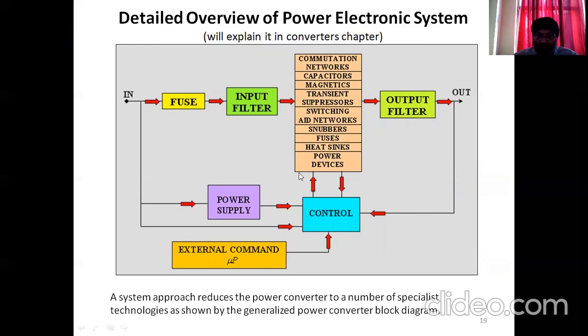And this power processor is being controlled by the controller over here. We already saw one building block in the previous slide. This building block controls or sends control signals and receives some output. Based on this, it makes decisions whether to increase the switching frequency or decrease the switching frequency.